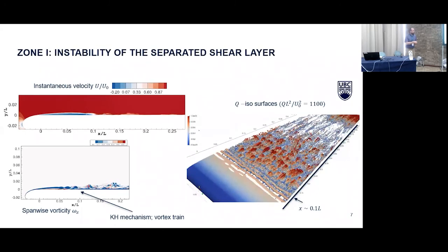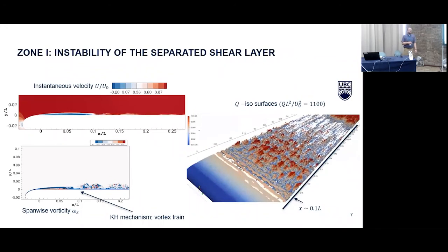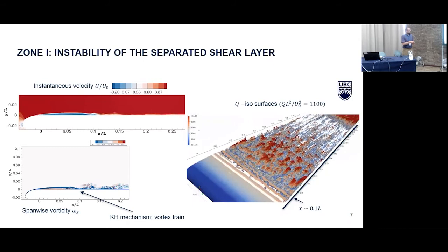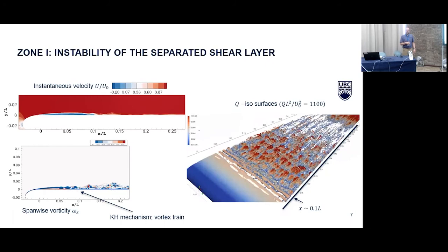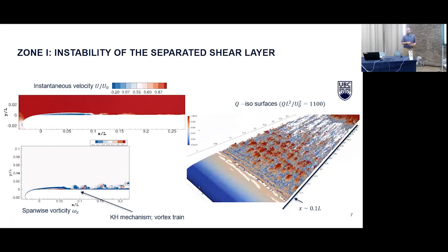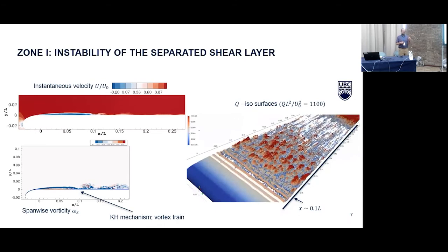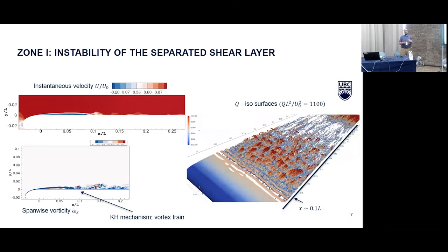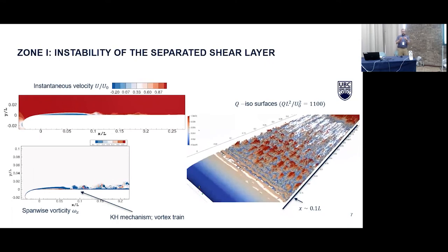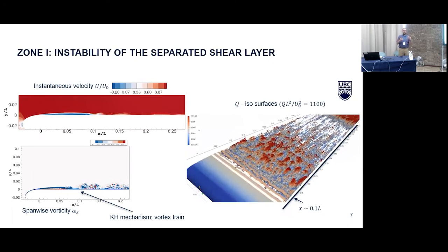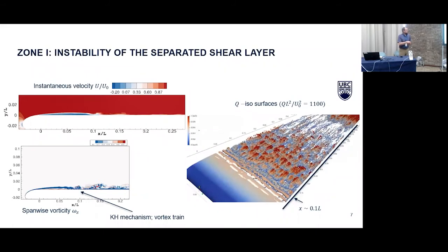And if we look at isocontours of Q criterion on the far right side, that's also what we can see. The span-wise homogeneity of these disturbances is sometimes clear and sometimes less clear. And what we actually are seeing is the inviscid instability interacting with a viscous instability in a different location of the flow that sometimes makes the inviscid instability a little bit less pronounced. Then the roll-up of those structures occurs very rapidly.